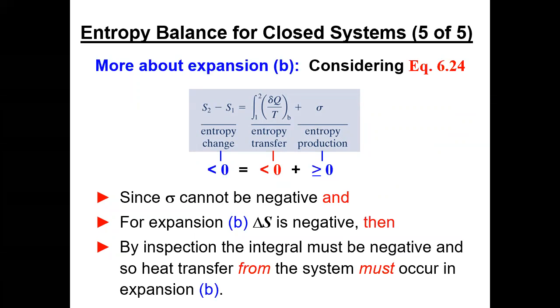Yes, sir. So this second term, this integral, that is negative equals negative sigma, right? Is that why the heat transfer needs to be exiting? Or well, negative, and so it cancels out to be a positive because those need to balance each other? Yeah, because we started out, we said, okay, it's adiabatic. So we set the Q term equal to 0. We calculated sigma, and it comes out to be negative. And you go, if I'm going to get between these two states, then I can't have this entropy destruction on this term. So this term comes out to be negative.